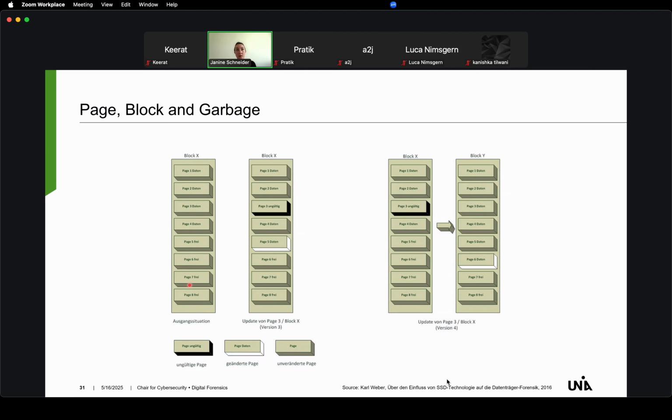You have the block, you want to update page 3, you write your updated page 3 to another page, and then you bind the LBA address to page 5. Strategy 4: copy the block to another block, considering the original has a free page, and while in the buffer, write to a new free page and bind the LBA address to the newly copied block.